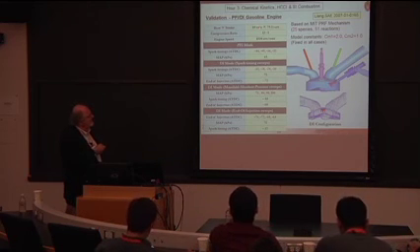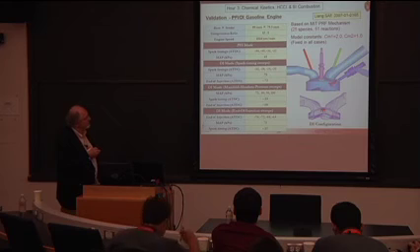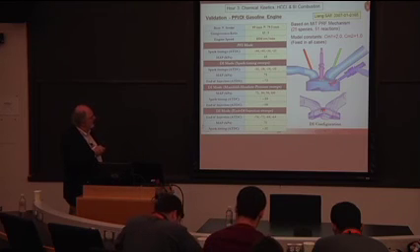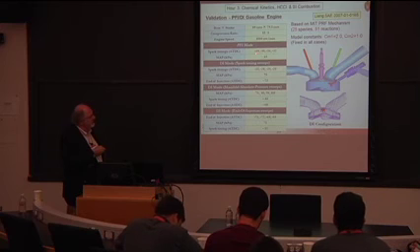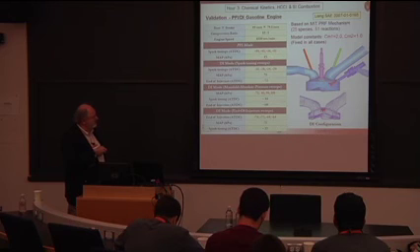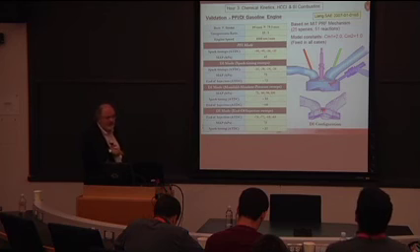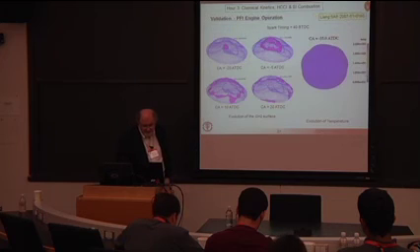It's an 89 millimeter bore, 79 millimeter stroke, 12:1 compression ratio, spark ignition engine at 1500 RPM. We're going to look at port fuel injection with spark timings from minus 44, that's 44 degrees before top dead center, up to 32 degrees. It's throttled, so the manifold pressure is 65 kPa. Remember, atmospheric is 101, right? So we throttled, and we're going to look at operation of this engine.